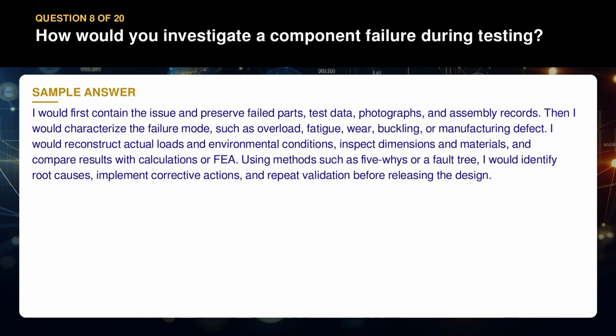Question 8. How would you investigate a component failure during testing? I would first contain the issue and preserve failed parts, test data, photographs, and assembly records. Then I would characterize the failure mode, such as overload, fatigue, wear, buckling, or manufacturing defect.